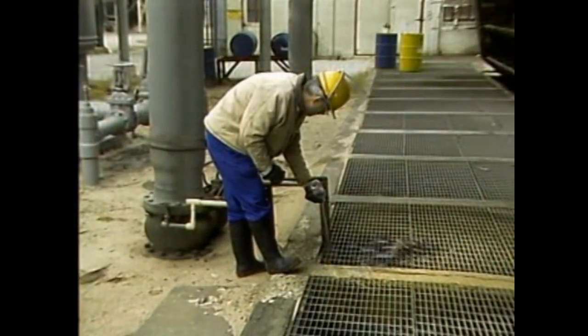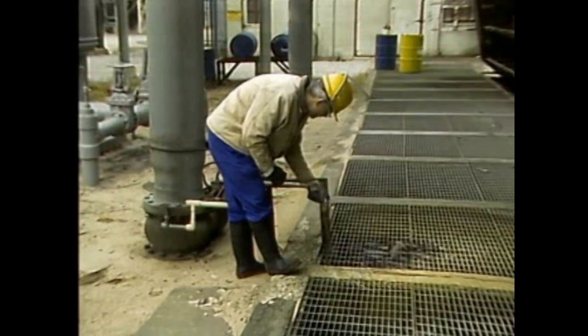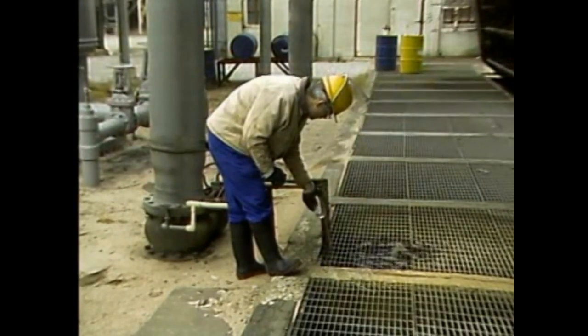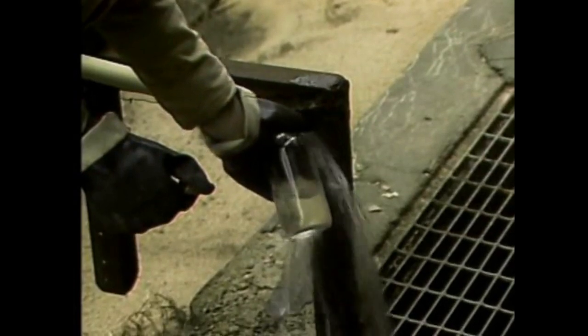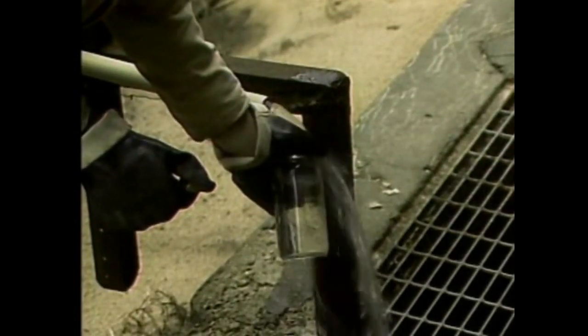Chemicals such as calcium or magnesium are often found as dissolved solids in cooling water. These impurities can become concentrated, come out of solution, and cause scale buildup. Scale buildup on the inside of a heat exchanger can reduce heat transfer and restrict water flow.